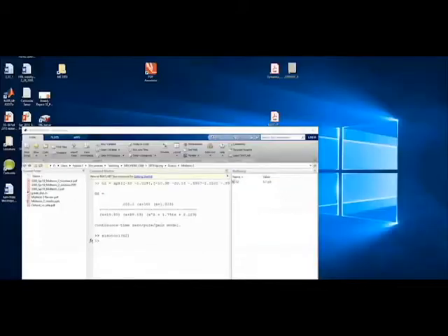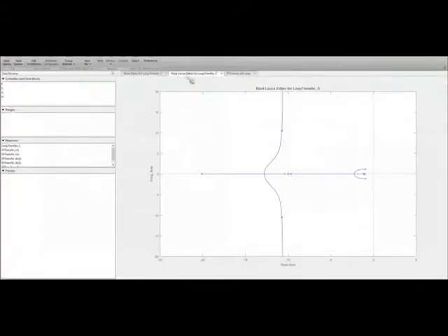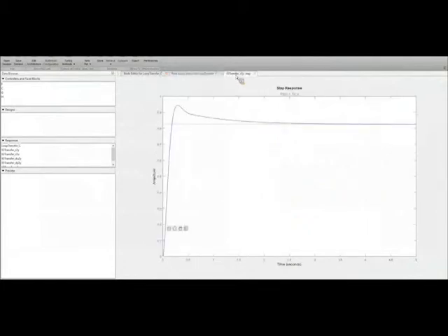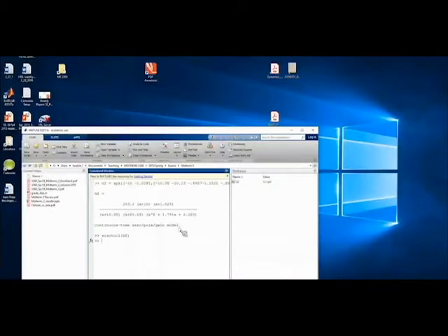Sorry, I forgot to remind everyone, the reason why we're trying to improve the steady state error here is that the transient response of the system was appropriate as determined by the specifications given in the problem statement. So the overshoot and the rise time were within limits. And then the deficiency in this controller was that the steady state error was too large. So we want the steady state error to a unit step reference, that means a reference of 1, to be 1%. So we want this E final value to be greater than 99.99 here. Right? We're currently around 0.82 for this. All right, so we selected alpha to make sure that was true.